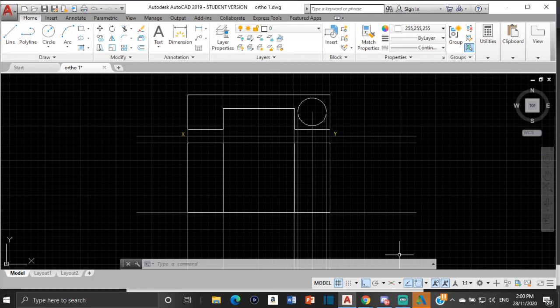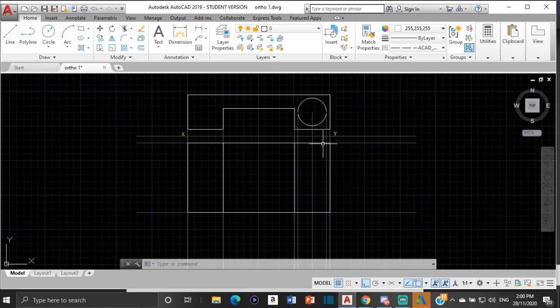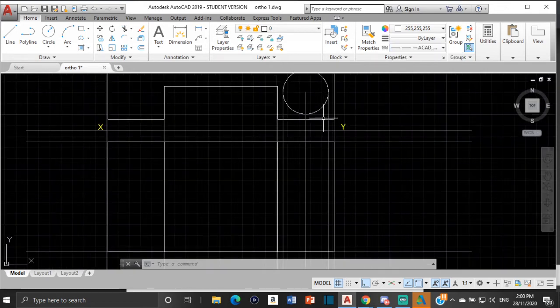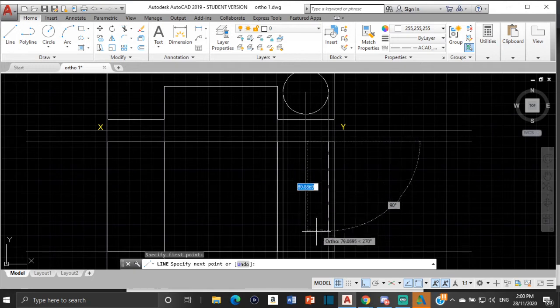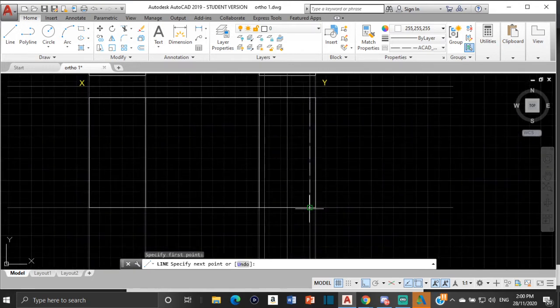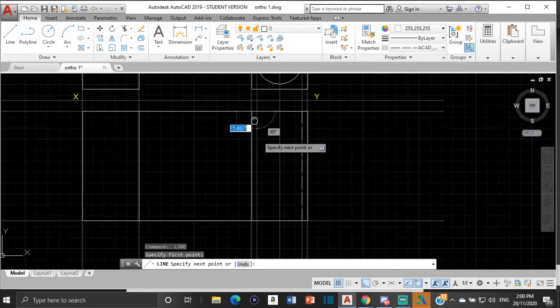because I wanted to show you how to go about representing holes in orthographic projection. So I would use a broken line for the edges. So where the hole is here, the edge here, this line, I would use a broken line like that. And the same thing for over this edge.